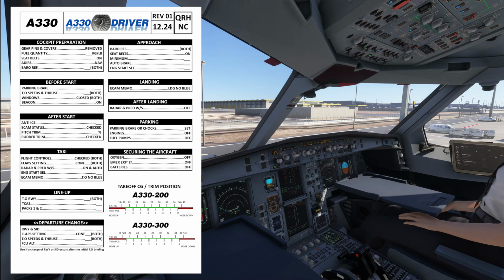Airbus normal checklists are of a non-action type. That means all actions should be completed from memory before the flight crew performs the checklist. Normally the pilot flying requests the checklist and the pilot monitoring actions it. The checklist actions are referred to as challenge and response type actions.